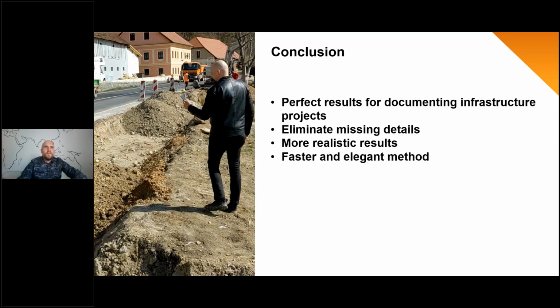It's also quite a fast and elegant method. Even with the technology we used when we were using ground control points for mapping, it was quite fast because we only had to record 8 ground control points with the GPS and then just record the video. But if in future we can eliminate the need to record the ground control points, then the technology will be especially fast and especially elegant.